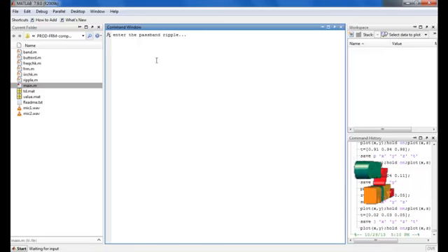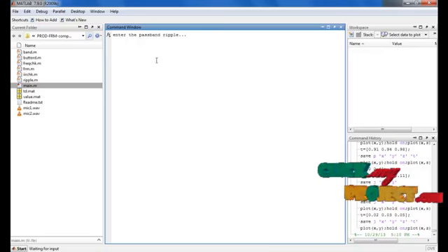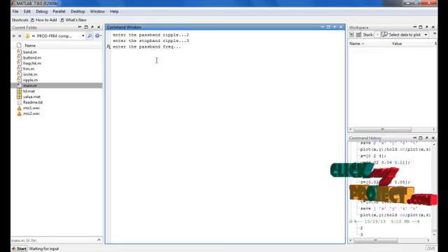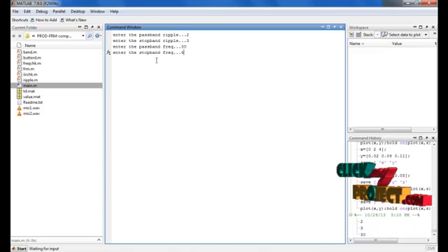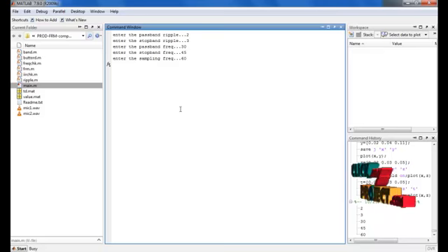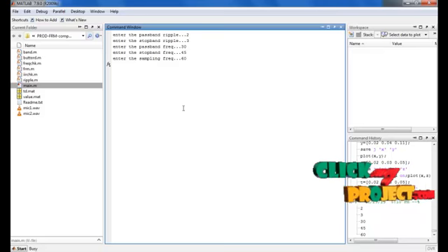So initially we have to provide our input to get the output. That is, it will ask for the passband ripple and the stopband ripple. For the stopband ripple, I am giving 3. Then it will ask for the passband frequency and the stopband frequency. Later, it will ask for the sampling frequency, which is used mainly in the concept of interpolation. After giving our input, the corresponding output graphs will be displayed.